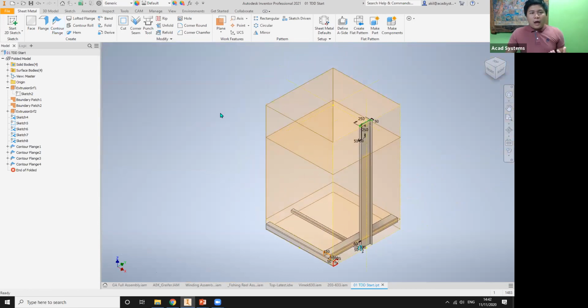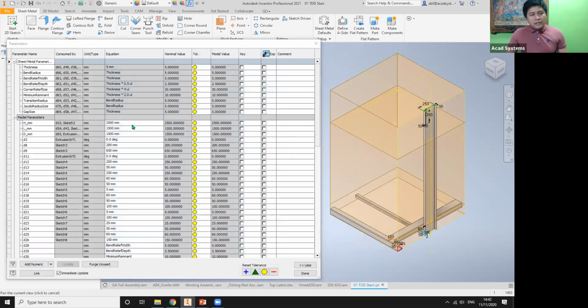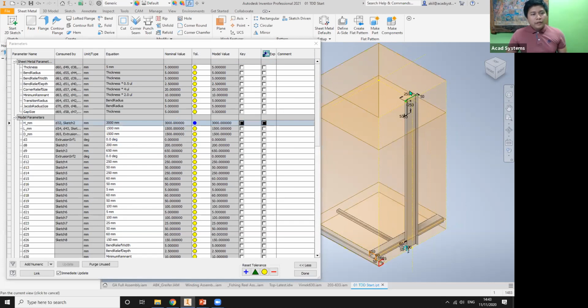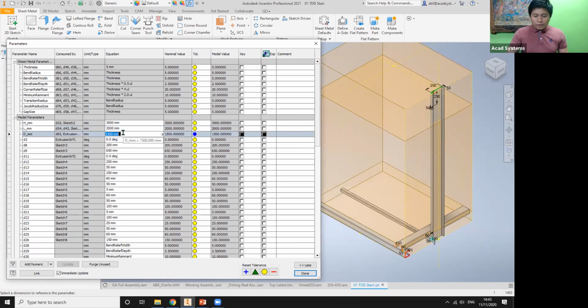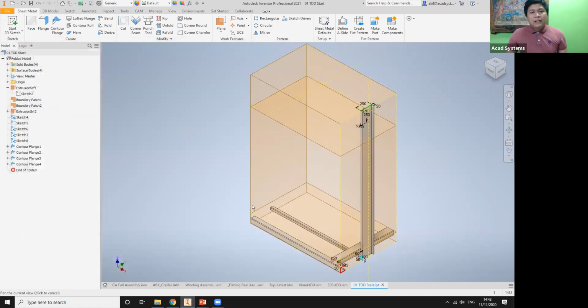Right, so basically what I'm trying to do is set the value here so that when I change this H to 3000, same like parametric modeling, this beam or this sheet metal will also follow. Same goes to here, 2000 also will follow. And over here, 1200, 1250 also follows. Right, so this will be the first step of modeling to create iLogic.